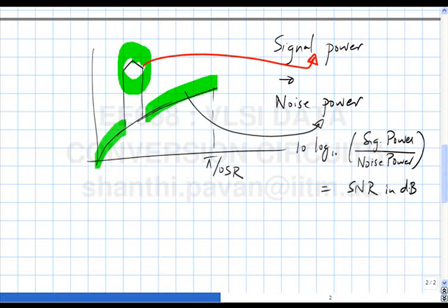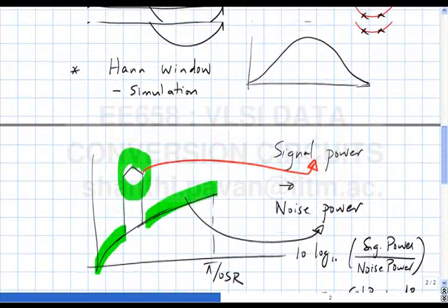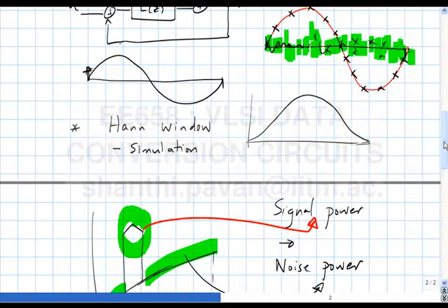You understand? So to come to his point, the point he made was that all this is very nice, provided the quantization noise is truly random and white. But clearly we know that the whole system is deterministic, there is nothing random about it at all, because given the input I can find the exact output by solving the loop. Fortunately it turns out, if you have a reasonably high order, say third order and higher, and you have multi-bit operation, that is the number of levels in the quantizer is large, this so-called quantization noise largely appears random.